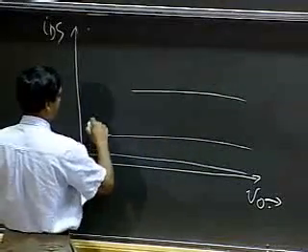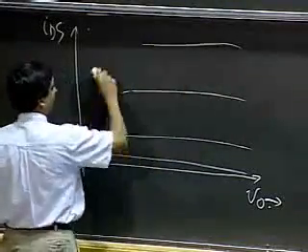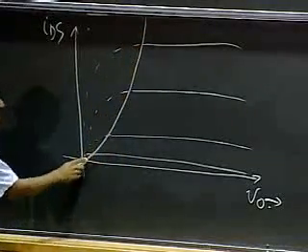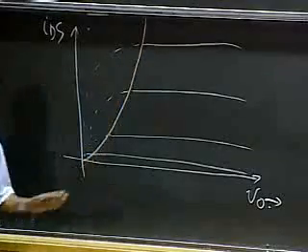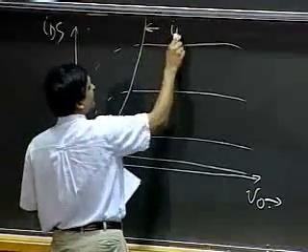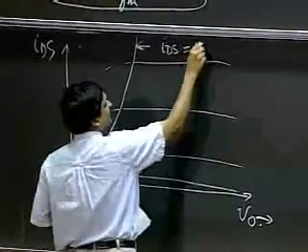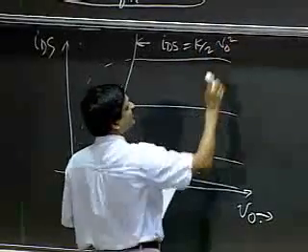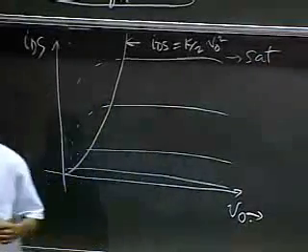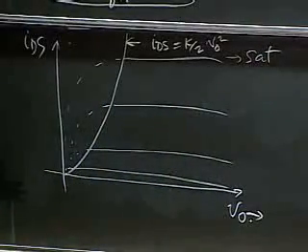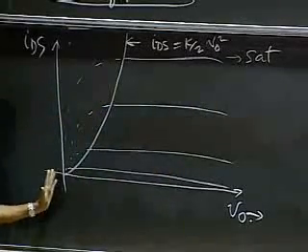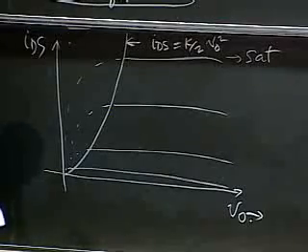And I said we draw that by first plotting the MOSFET curves, and we know that at some point the MOSFET gets into saturation. So this curve was IDS equals K by 2 V naught squared. And to the right side of the curve, the MOSFET is in saturation. And we said we're going to adhere to the saturation discipline and operate in this regime. Okay, when the MOSFET gets into this region, it is in its triode region.